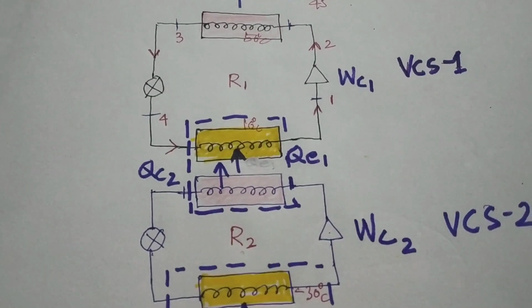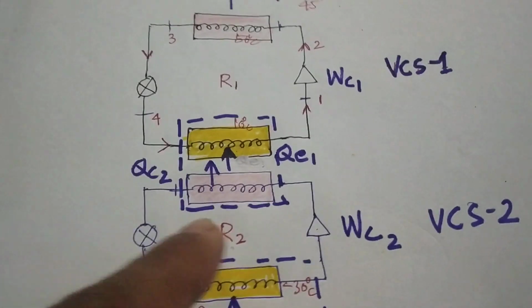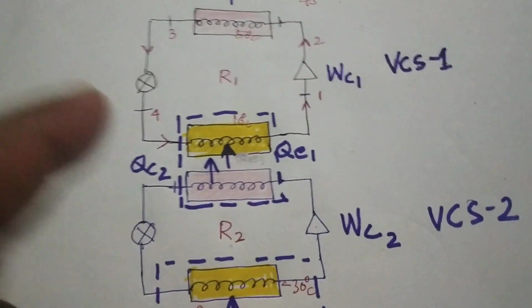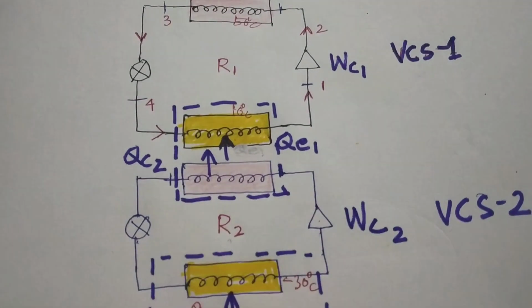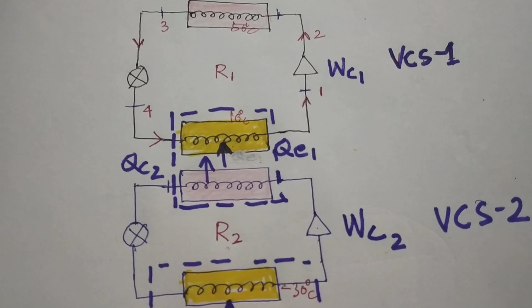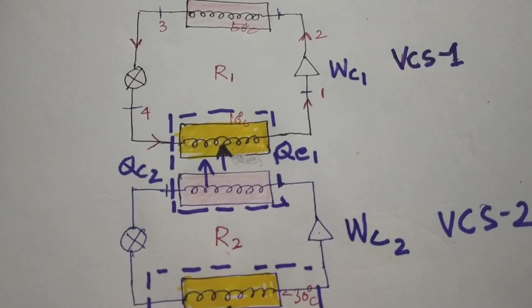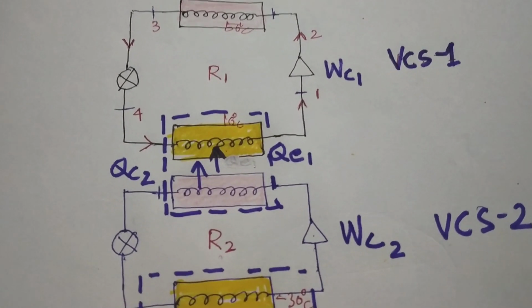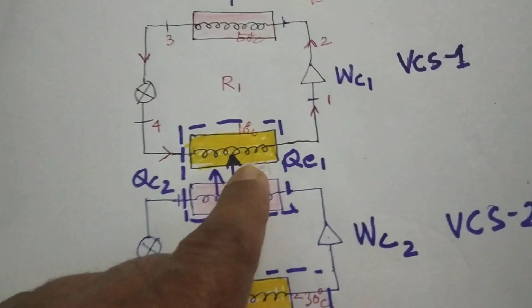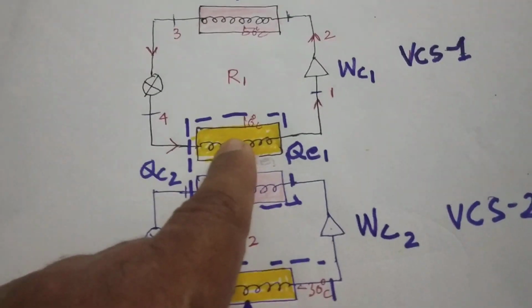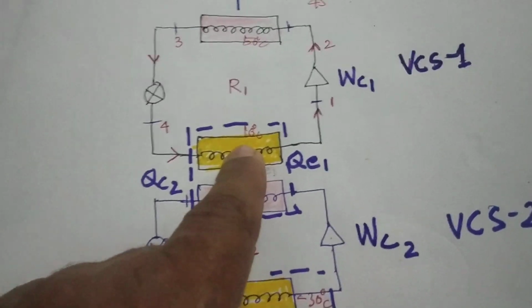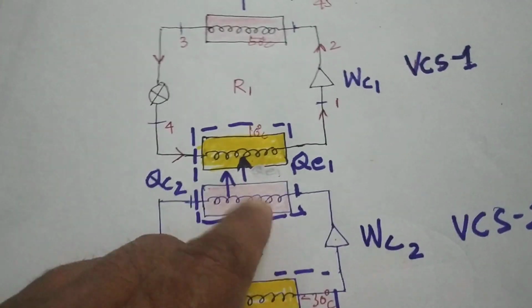Here we are coupling the two systems by how it is joined, because the heat rejected by condenser number 2 cannot go anywhere but be absorbed by evaporator number 1. So this evaporator will be absorbing heat from the condenser, and this heat absorbed is not from any other space but here.